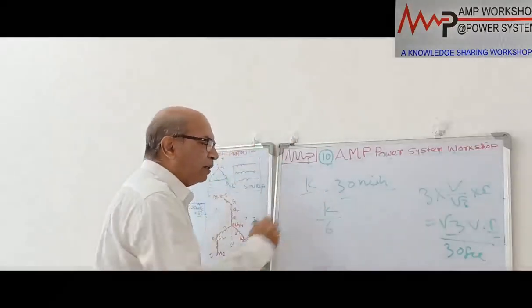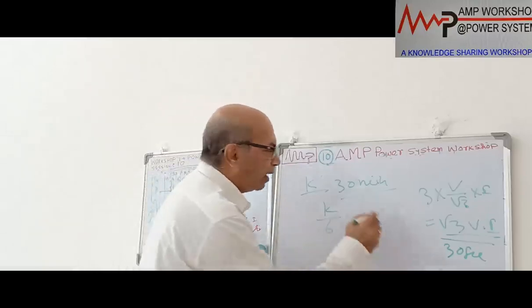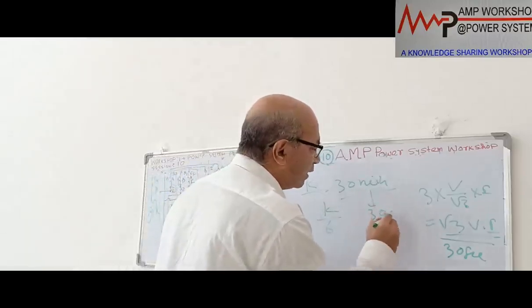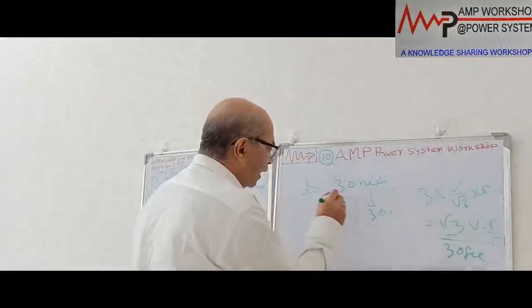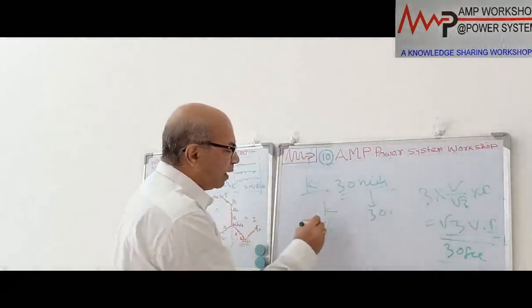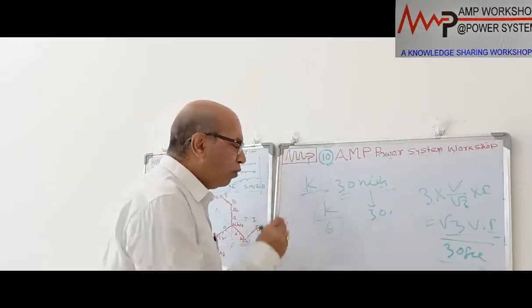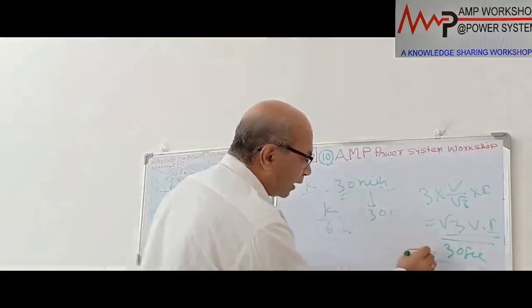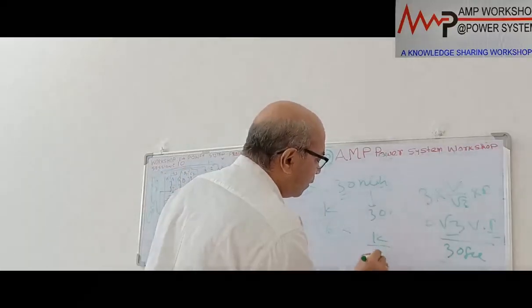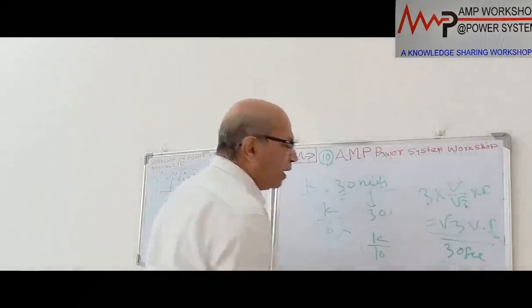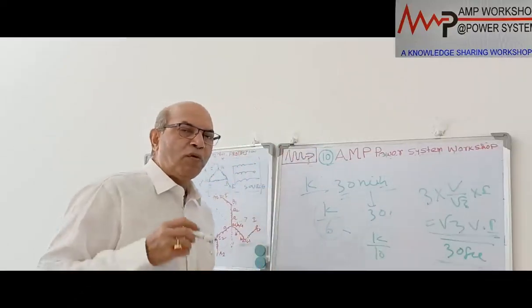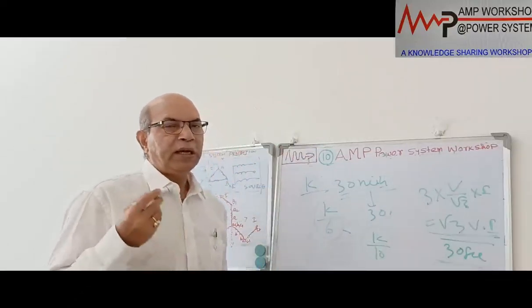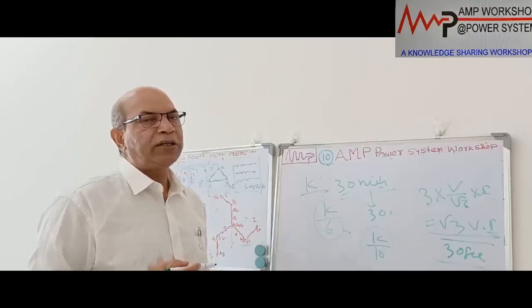Okay, based on that guideline, as it is only 30 seconds, not 30 minutes, it is 30 seconds only our requirement. 30 minutes rating will be kVA by 1 by 6 of the continuous rating. We normally consider this 30 second rating as kVA by 10. So what is the kVA capacity coming as per this calculation? We take 1/10 of that as the rating for this grounding transformer.